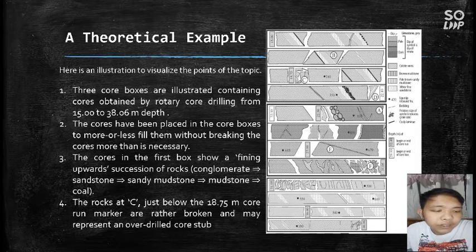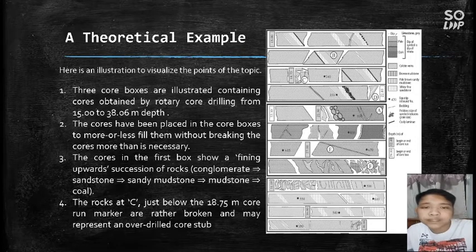The implication is that the breaks in the core above and below 31.05 meters are a consequence of natural phenomena and not the drilling itself. The same remark could apply to the broken core just above 38.06 meters. But here, it might also be the core cracking in the vicinity of the core spring on breaking off of the core to pull it to the surface.